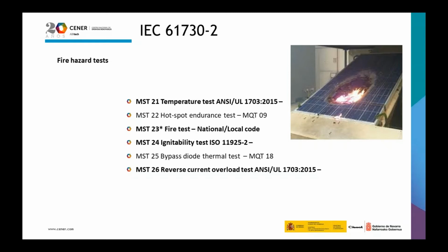The fire test, MST 23. The PV modules may be exposed to external fire conditions and therefore should be tested for the fire resistance characteristics when exposed to a fire originated from outside of the PV module. Through this test, we check the fire resistance class of the PV module.